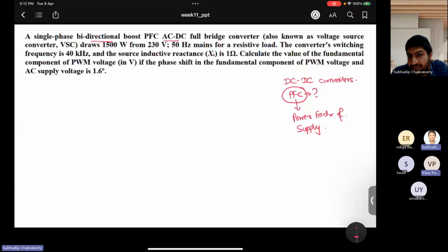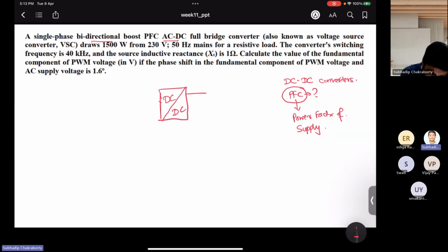Only we can ensure that the load rating is within the rating of the designed system. Whatever system we are using, the load should be within that rating. But if you want to regulate the load power factor, you cannot do it directly. So what you can do is interface some converter, feed the load that much power as it requires, and also make it appear to the supply as if your load is behaving like a unity power factor load. So with some converter, for example, we are talking about DC loads or AC loads also.